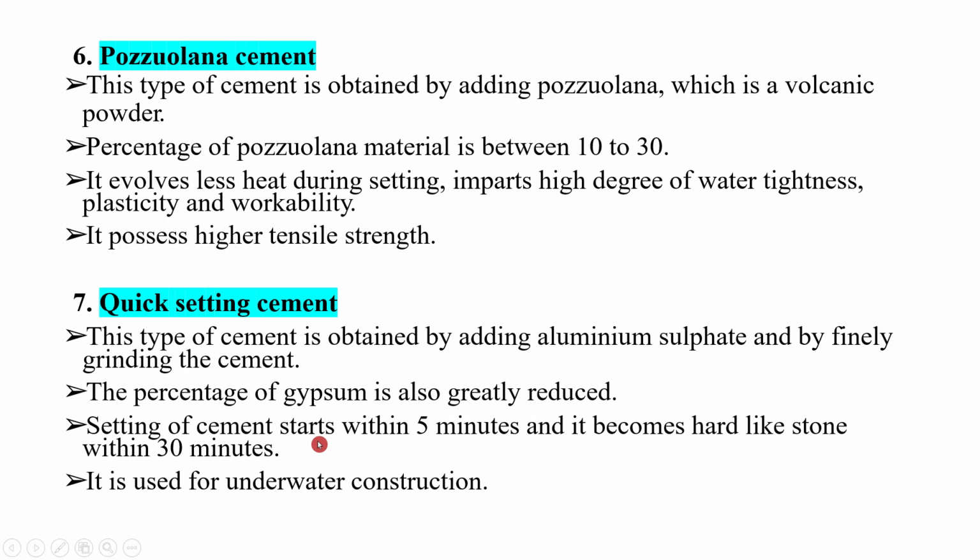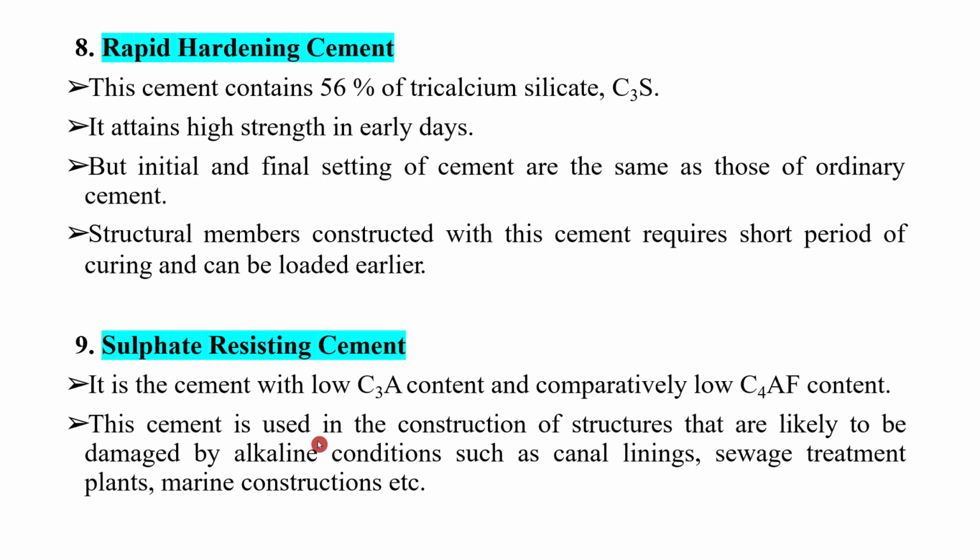So both the initial and final setting time is quick in the case of quick setting cement, and it is used for the underwater construction. That means we don't have much time, because for underwater construction we need to empty the water from that place. So we can't hold the water for a long time. So that's why we are going for a quick setting cement.